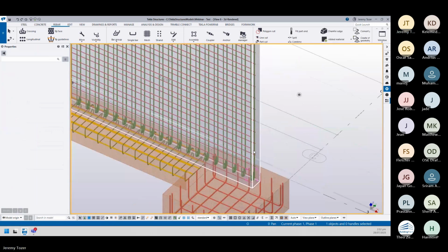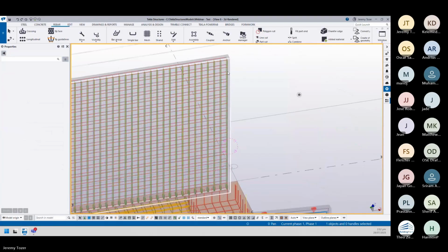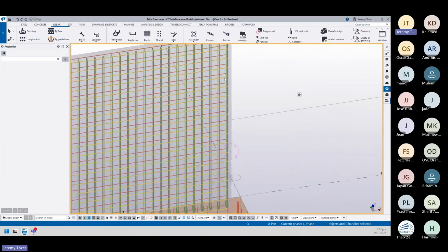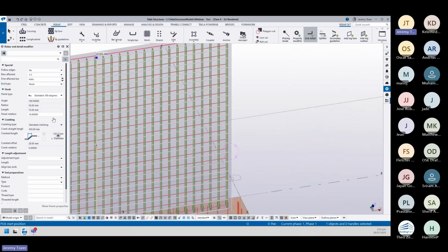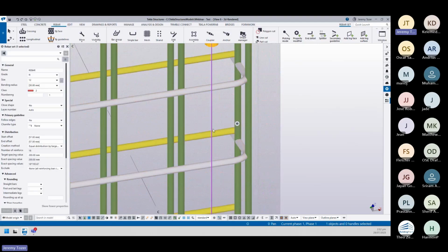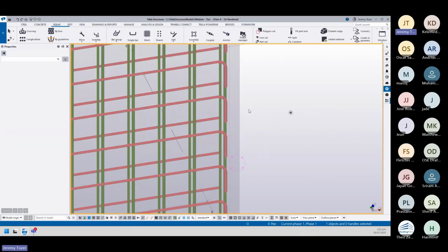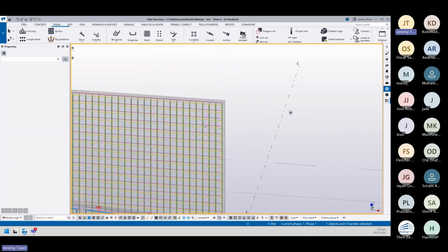On the bottom, and then you would do your top bar, and do your returns on your other sides, 90 degrees in detail. Now you can see it's returning them the wrong way. So I'm going to put a 90-degree bar rotation on that, and then you can do exactly the same as I did before.